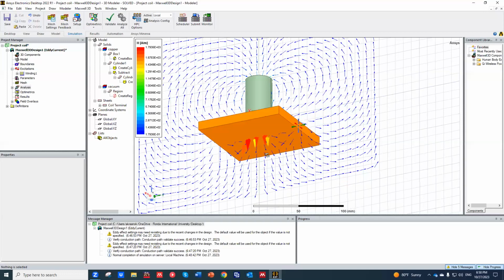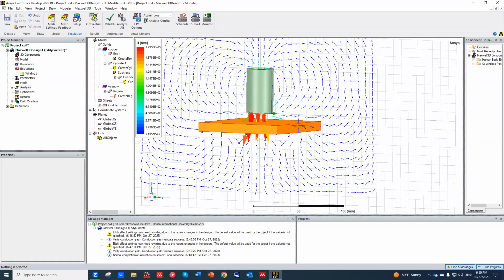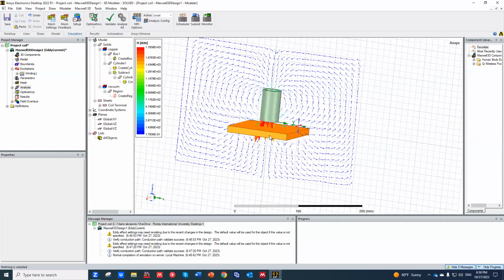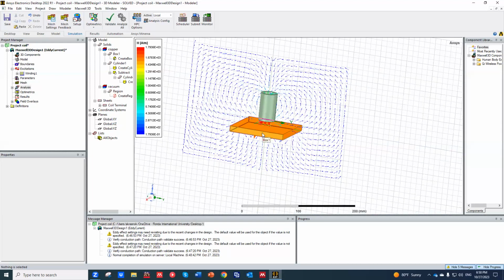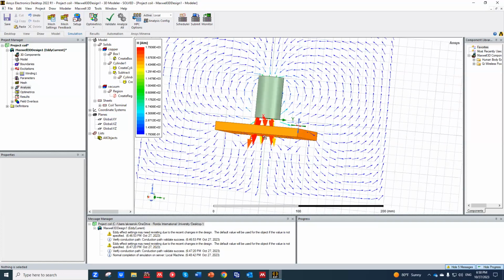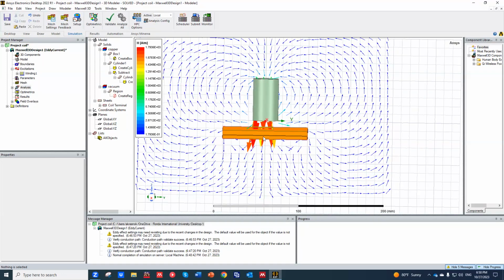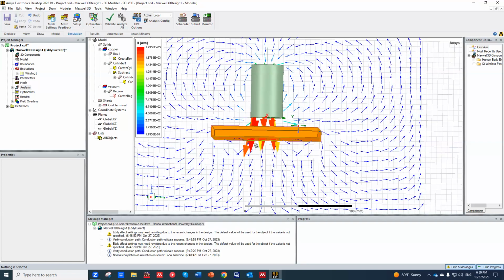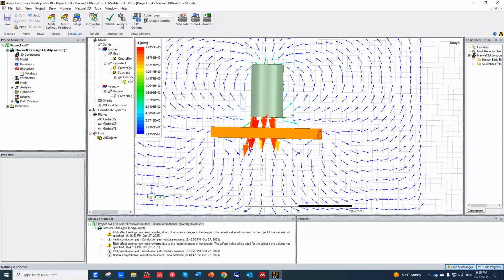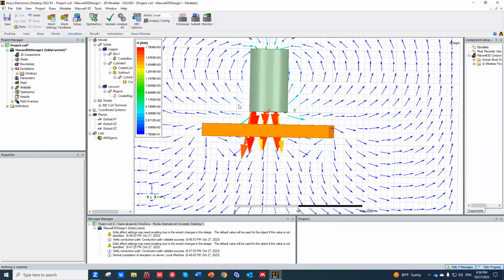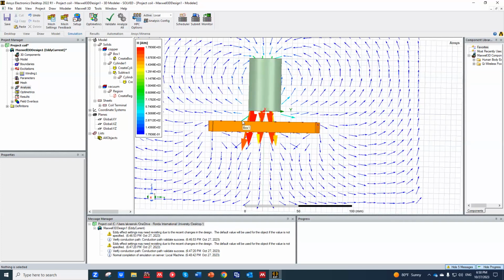Okay, and it creates the magnetic field. So we see that the presence of the metallic slab actually changes the distribution of the magnetic field. So it is not really like nothing, right? Not empty space. Why? Well, because as we will see now, this metallic slab gets the eddy currents.